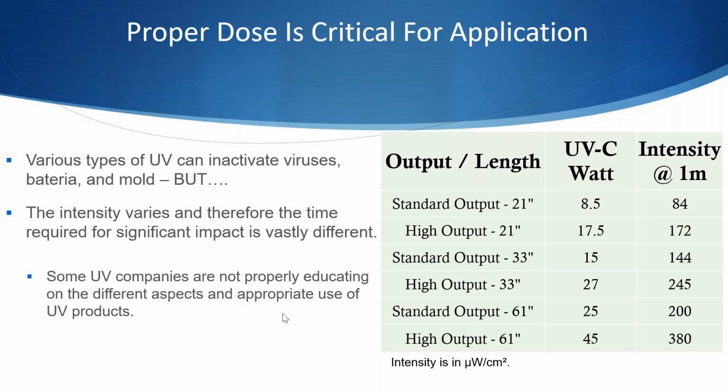Airflow, because of the time factor of the equation, is very important also. So most installations prior to coronavirus, the coil cleaning type, were installed perpendicular with the airflow, and any air volume passing by them usually was 500 feet per minute or less, because it was already limited by filtration and coils and humidifiers, things like that in the unit that can't be used at high velocity either.